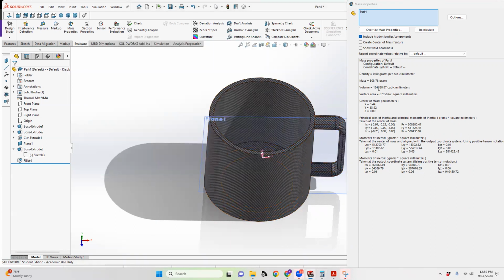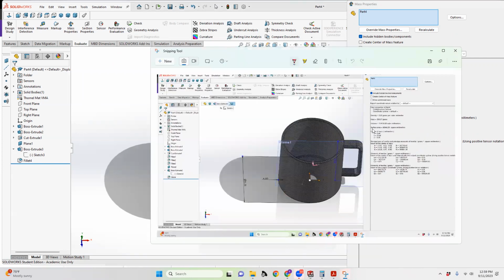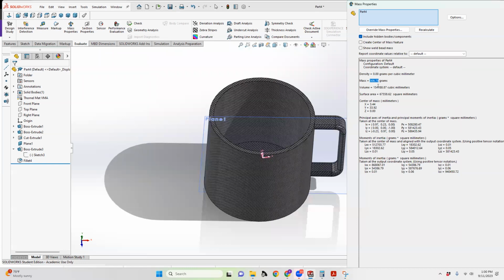How it's actually lighter with more material is because of SolidWorks. So the volume is slightly higher, but this is also why it's important to have a screenshot that you can reference and say, oh, okay, this was 1544.34, 1543.88. So this is a lesser volume, and yet somehow the mass is even less where it should actually be more, because those fillets should have taken away material, right? So all of those kinds of little features can push you outside that 1% boundary very quickly.